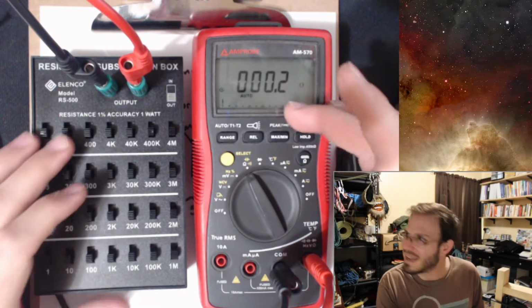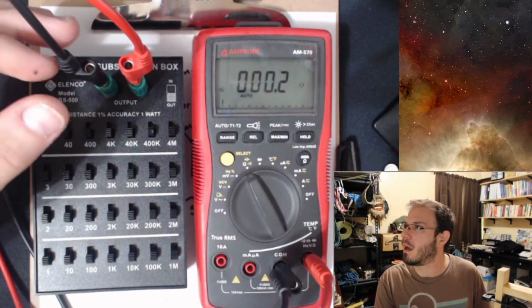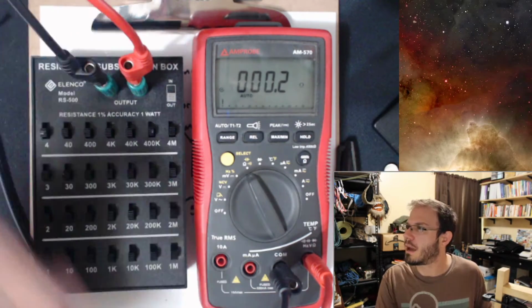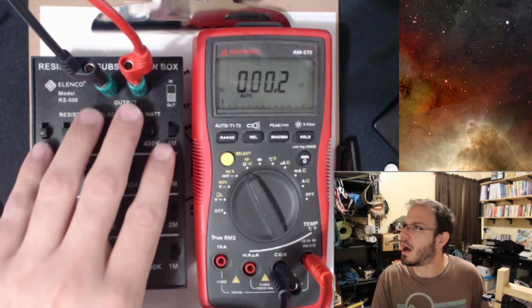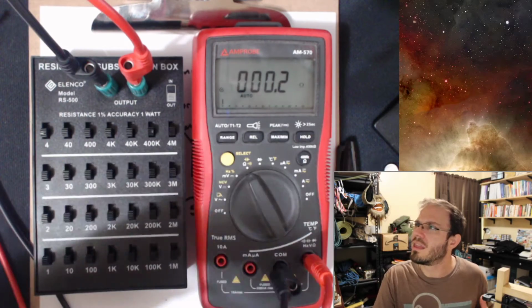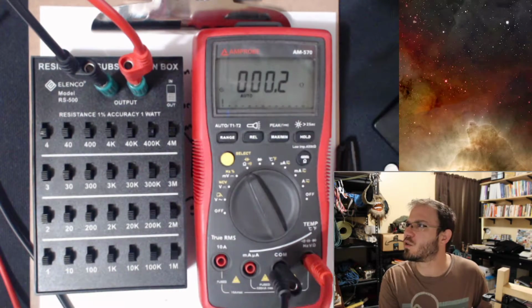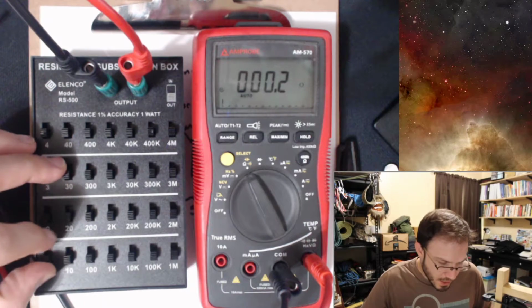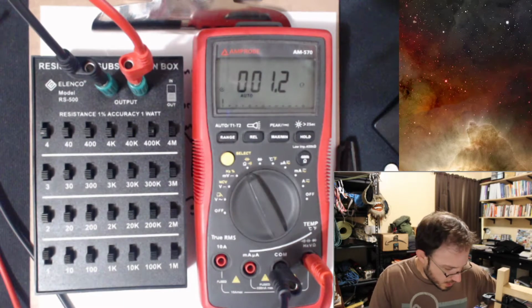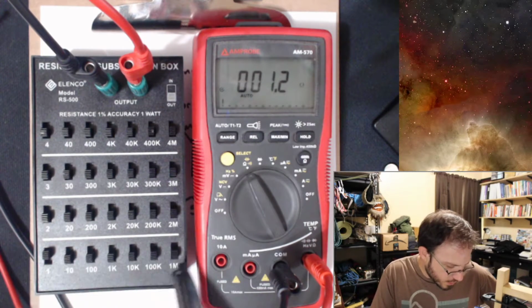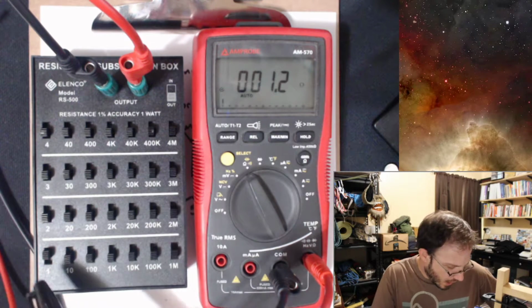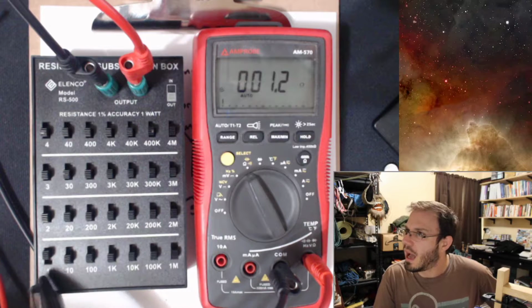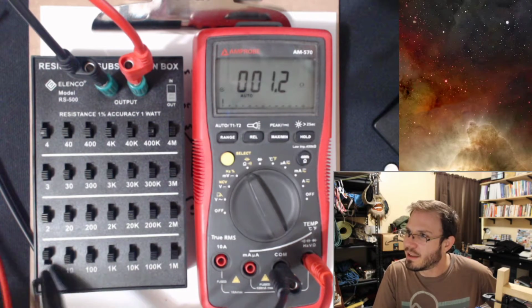but we just recognize that there is some error, coming from the measurement from the multimeter and from some resistance in these wires. Inside this box is a bunch of wires as well. There's going to be some error, and it is quite small. Okay, so let's flip up the 1. What I just did is all of these resistors that are built into this box are now disabled, except for the 1 ohm. I unshorted the 1 ohm.